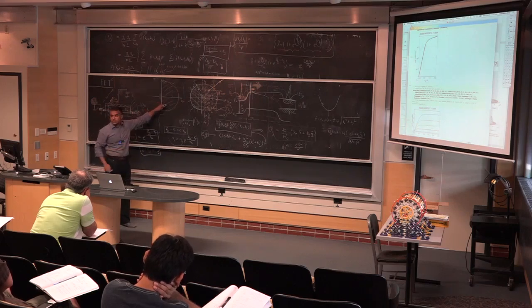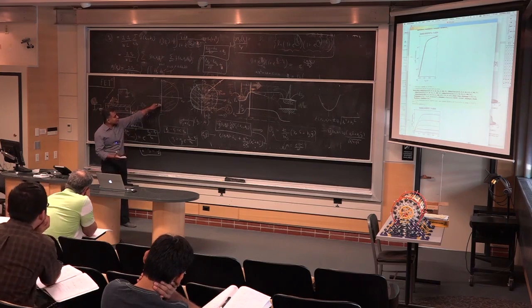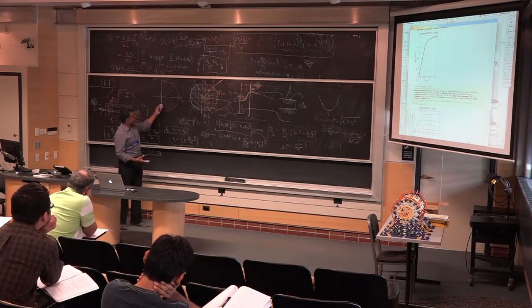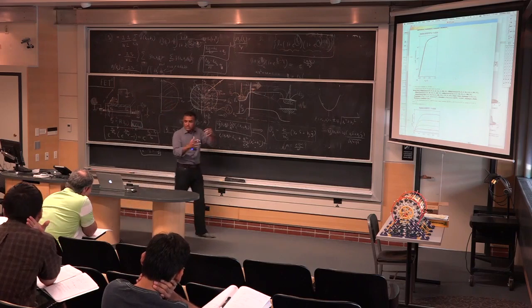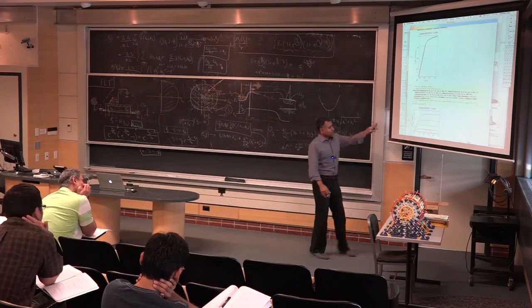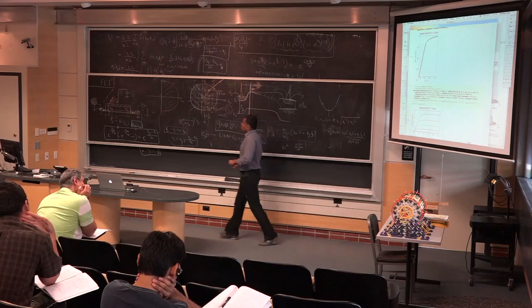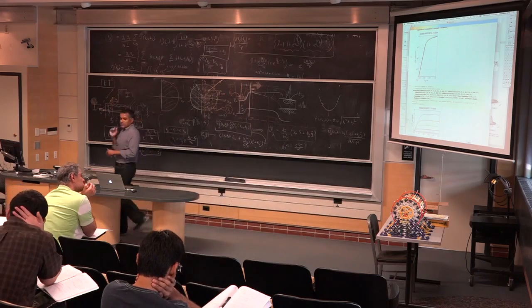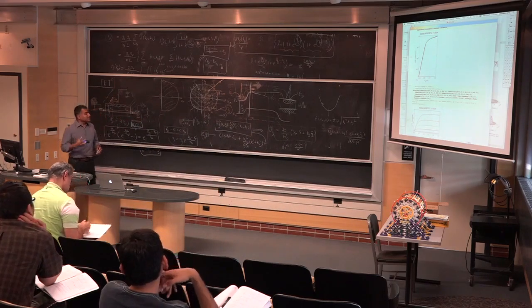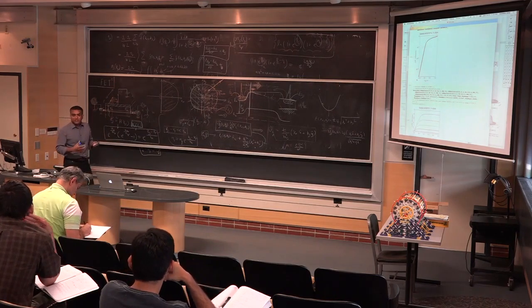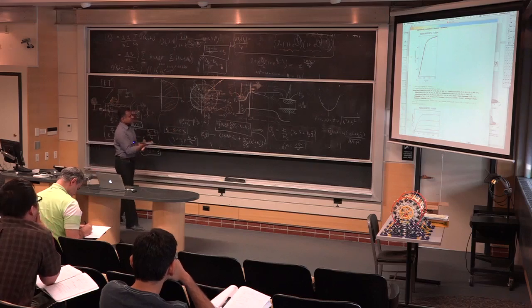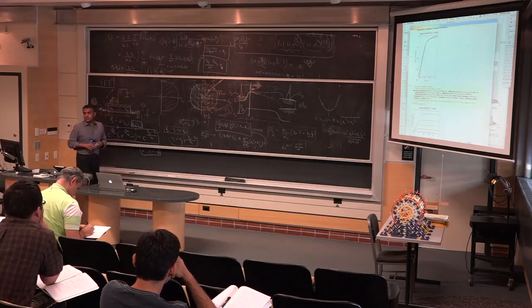That's the reason why the current is saturating, because the number of electrons is completely controlled by the gate. And once you fill this, there's nothing else to do. You can apply more drain voltage, nothing else is happening. So it just gets locked here in some sense. It's a simple picture, but it works pretty well. There are obviously complications to it, meaning if you apply a very large drain voltage, there'll be breakdown and tunneling and that sort of other things. And those things have been turned around to make devices of the future. But in the devices of today, this seems to explain this whole business here.